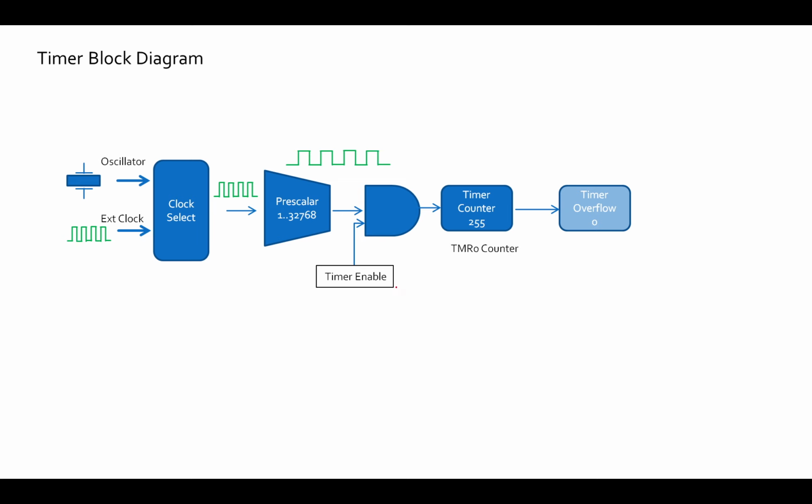Now the timer zero counter is getting a little bit close to what's the important part. There's an overflow at 0. And if you notice that this changed to a 1, let's go back. It was 0 before. Only when it goes to 0 does the overflow get set. So once that gets set, we can test for that. And if I've got the interrupt enabled, I get a timer overflow interrupt.